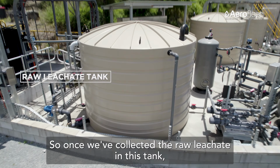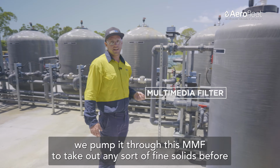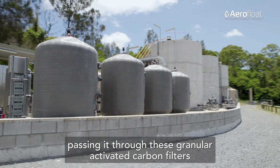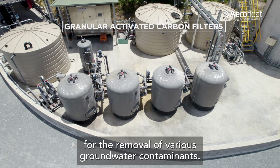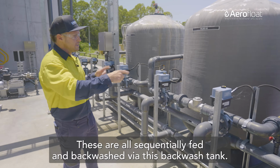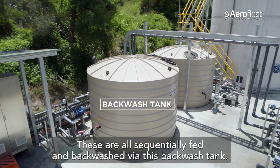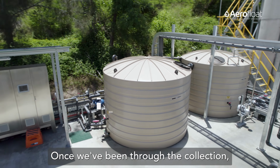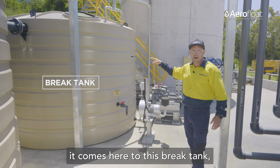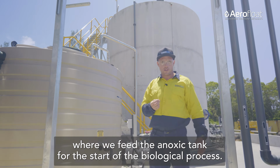So once we've collected the raw leachate in this tank, we pump it through this MMF to take out any sort of fine solids before passing it through these granular activated carbon filters for the removal of various groundwater contaminants. These are all sequentially fed and backwashed via this backwash tank. Once we've been through the collection, filtration, backwash storage, it comes here to this break tank where we feed the anoxic tank for the start of the biological process.